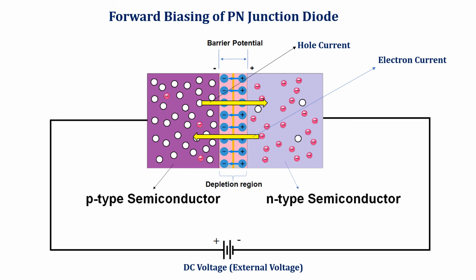The depletion layer around the p-n junction is decreased under the forward biased condition. If the forward bias voltage is increased to a particular value, the depletion region becomes very narrow because of the rush of majority carriers crossing the junction. These large number of majority carriers constitute a current called forward current.